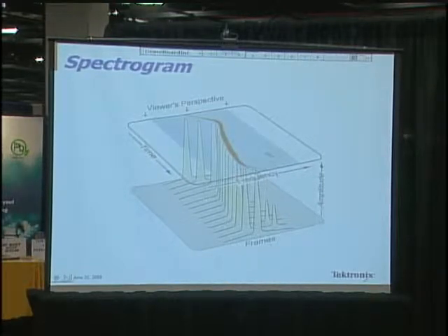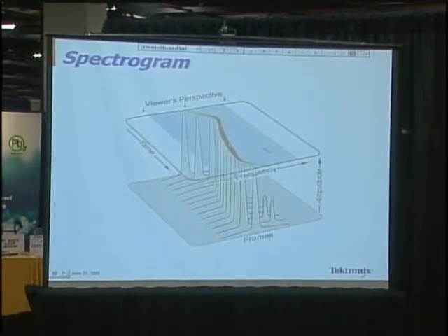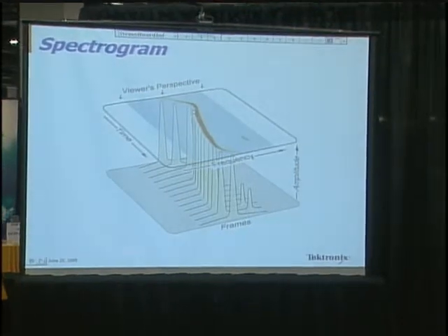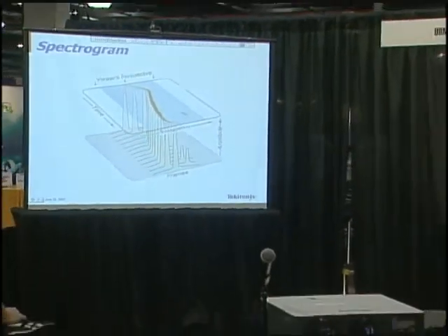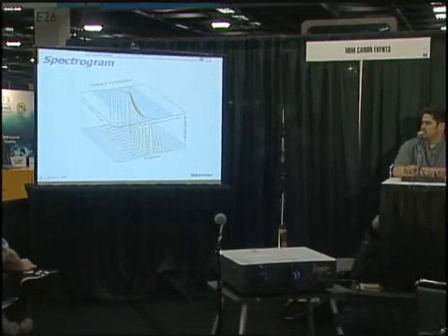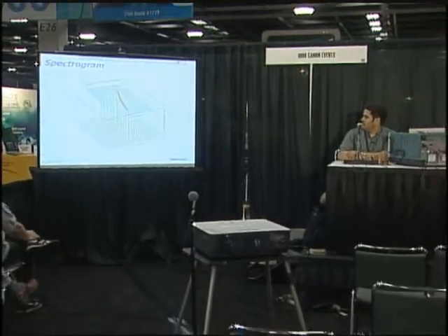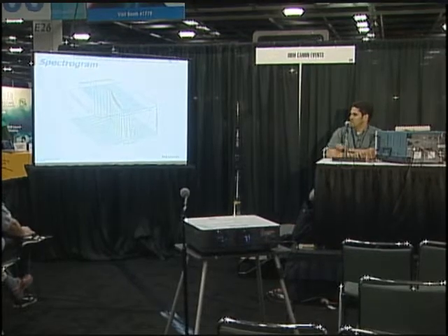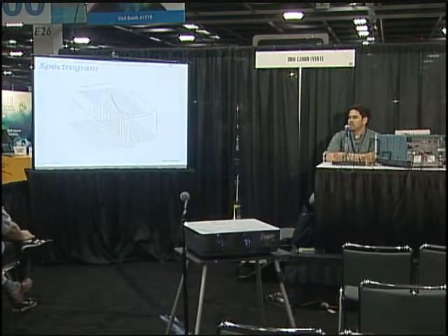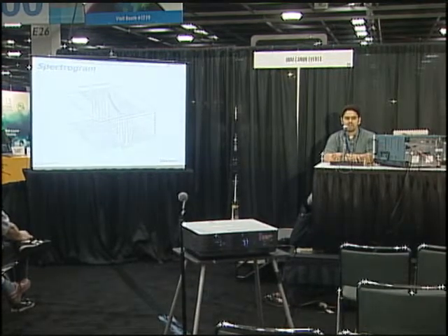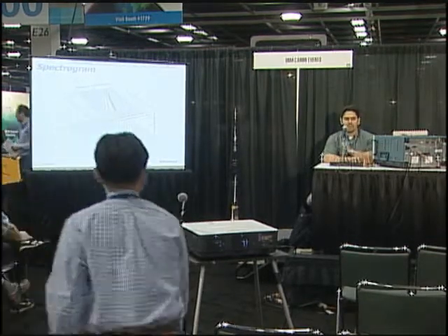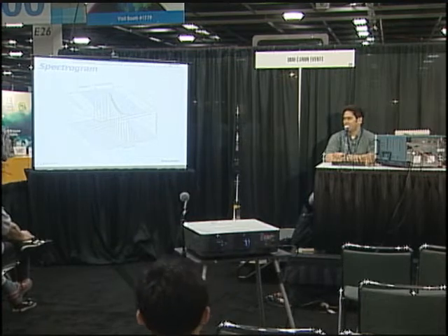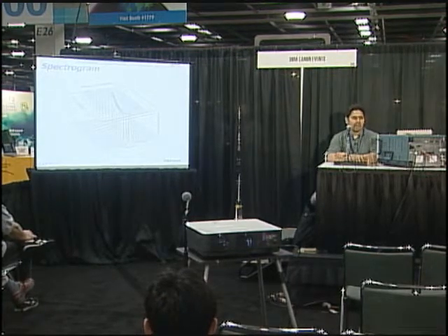So you can see that the main signal here is wandering in frequency, and that's very obvious when you look at the spectrogram. But if you see it one by one, that might be a little hard to realize. Also, you see this little green line here? It's a transient, which is a short duration spectrum event, and it's very easy to see in the spectrogram, while in the regular spectrum analyzer view, it would have been just a flash that showed up and disappeared, and very hard to see.